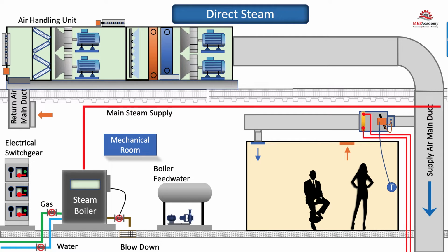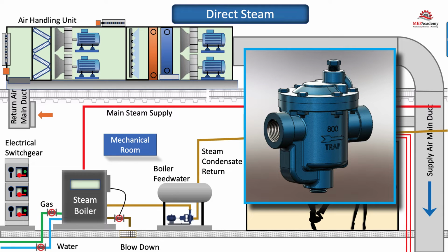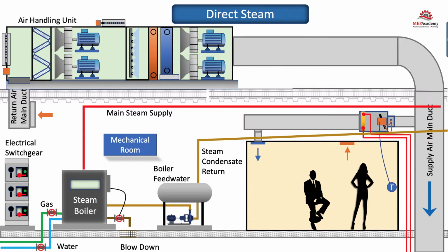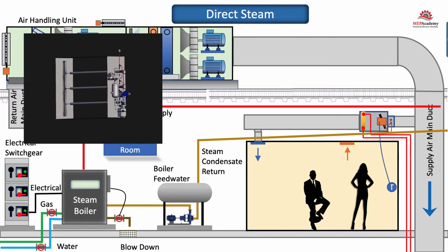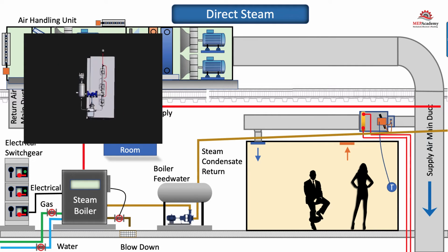Then we need to pipe the condensate return piping, which basically follows the steam piping, as we'll need steam traps at every piece of equipment and every so often to remove condensate that occurs in the steam piping. We'll need to run conduit and wire over to the steam boiler to provide power to run the boiler and controls. If the project has all of this, then the first choice for adding a humidifier would be the direct steam type, as everything you need is already in place.